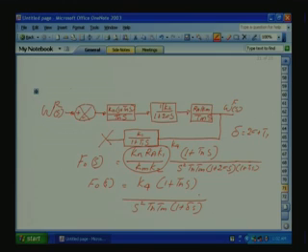This we are trying to find out another way of optimizing the loop by choosing Kn and Tn using the symmetric optimization using graphical methods. So this is the open loop gain. Now from the control system point of view, the system will be stable if the open loop gain at the unity gain crossover frequency goes down by minus 20 dB per decade, and at the gain crossover frequency we have a sufficient phase margin. We can stabilize the system.